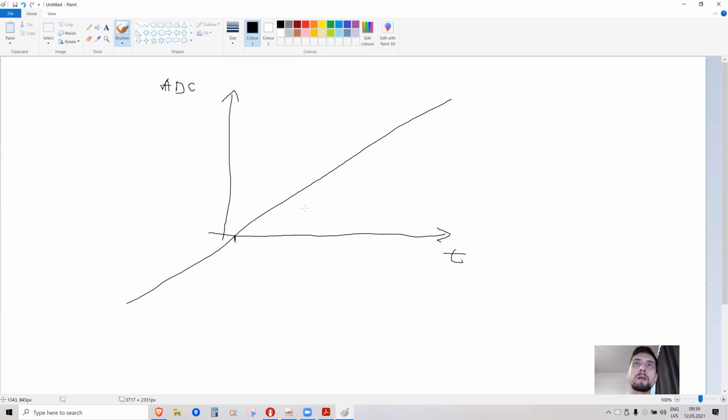We don't know where this point is or anything, but we know that the angle of this slope is such that basically the tangent of this is minus 1.92 millivolts, or, well, since I put ADC points here, I better change it from millivolts to ADC points, so it's minus 6.3 ADCs per degree Celsius, or per Kelvin.